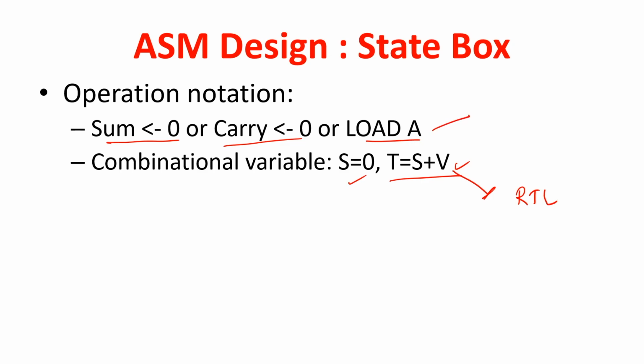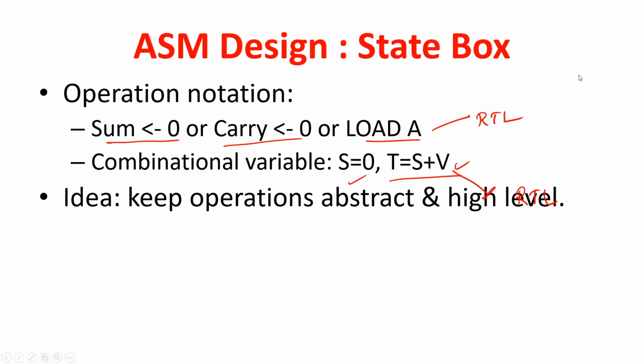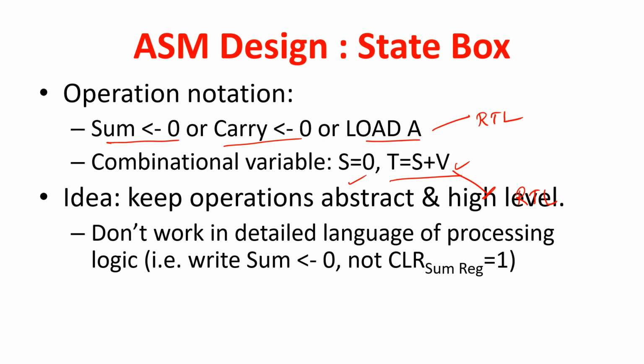Load A, loading A from external values, is also an RTL kind of specification. Because of these reasons, we say we are specifying at the RTL level. So the idea is to keep the operations abstract and high level, and not work in the detailed language of processing logic.